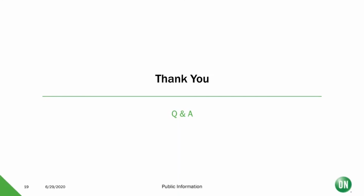Okay. Another question that we have here: is there any indication of the message propagation time through the system? That's a good question. Depending on the number of hops a message has to take, you get a certain sense for how long a message would take to go from a source to destination. As part of the mesh network itself, when you configure the network, there are periodic heartbeat messages sent among all the nodes that help to get a sense for how far the nodes are. And this is where the TTL field, the time to live field that is encapsulated in each packet, comes into play.